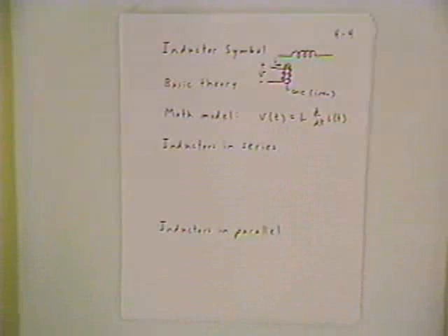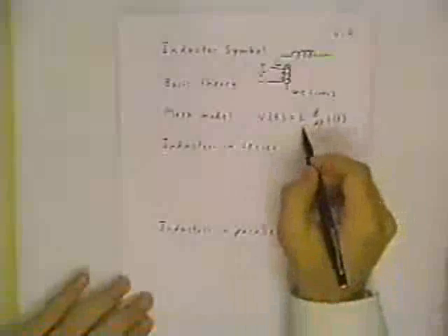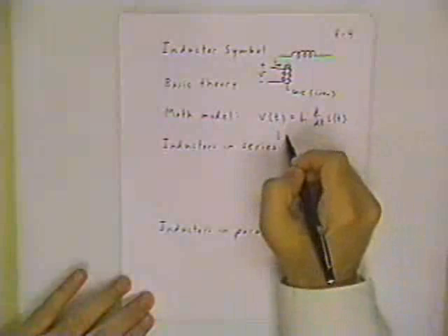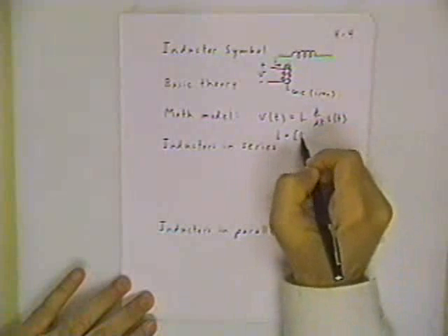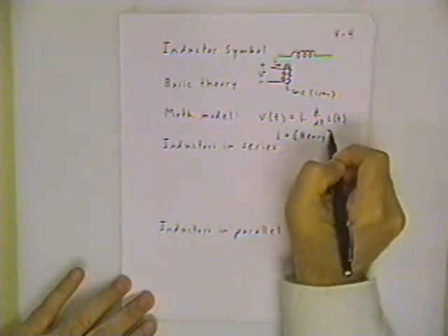Frankly, I find it much easier to understand and discuss capacitors with you. So the thing to do is understand the basic theory of the parallel plate capacitor to help you remember that linear model, that the capacitor current I is C dV/dt. Once you've figured out and remembered the capacitor model, all you have to do is remember that the inductor is the companion component, and you just reverse the roles of V and I. You replace the capacitance with the inductance, and that's all there is to it. For an inductor, you have an element parameter called the inductance, L, in henries.